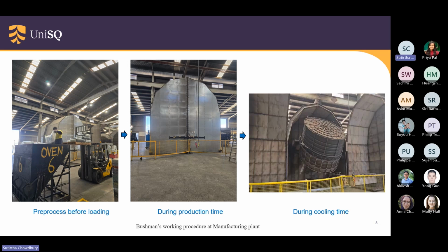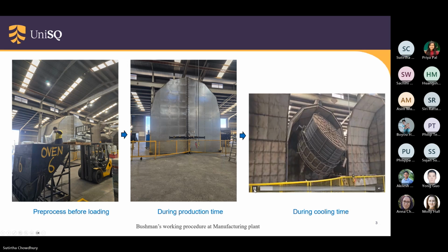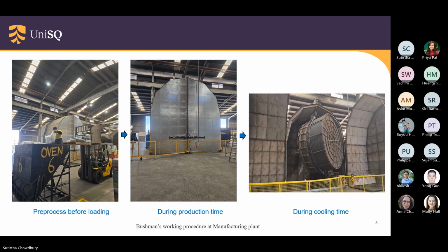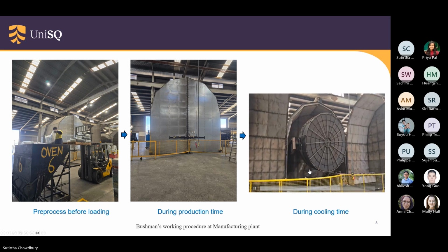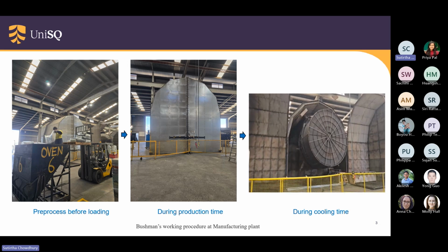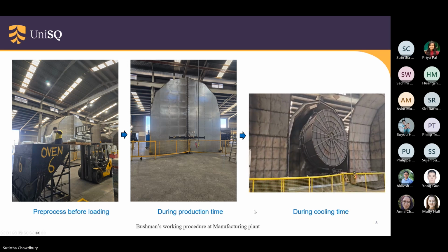They will start their curing process. The curing process will run up to 45 minutes, and the mold needs to get to 150 degrees Celsius to melt the polyethylene powders. After 45 minutes, they start the cooling process, a natural cooling process, which you can see in this video. They are generally using biaxial rotation for this process.